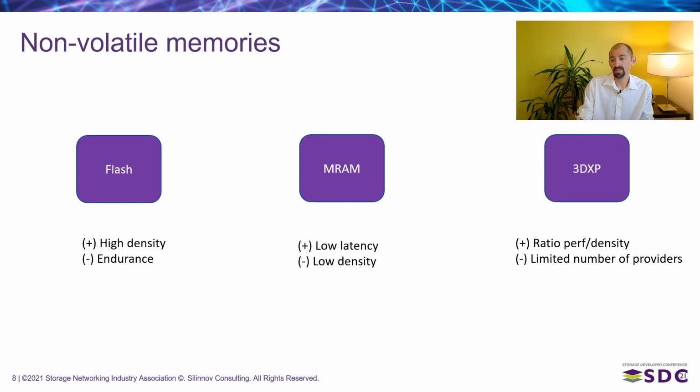In the memory landscape, computational storage is obviously based on the use of NAND flash. For the latest CSD products on the market, the trend is even to use QLC, since it comes with the highest density. So we can find a few terabytes of memory directly coupled to the embedded computing in the CSD.